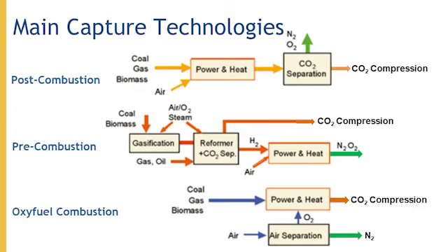The last one, the oxy-fuel combustion, is one of the more recent developments. Here, the modification is actually in the airstream. So if you separate the airstream into oxygen and nitrogen, you're able to burn your fuel more effectively and produce a higher concentration of CO2.